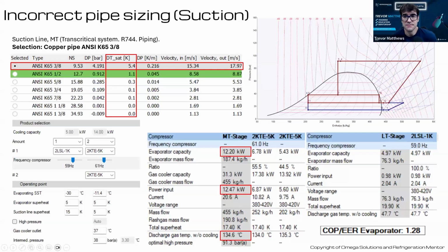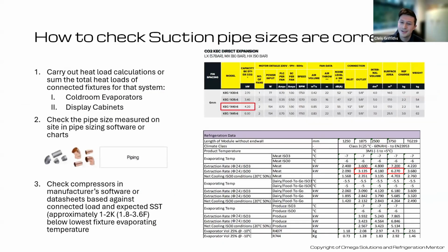Yeah. What can we do instead? Well, there's not a lot we can do in the field. If you're up against a problem like this, you need to start jotting some information down and then doing some homework. So unless you can see immediately, if you go from a 5/8 pipe down to a 3/8 pipe and back up to a 5/8 pipe, well, there's obviously going to be some sort of restriction, excessive pressure drop there.